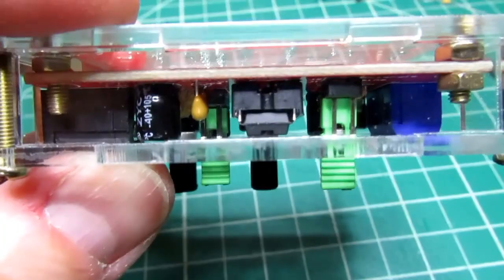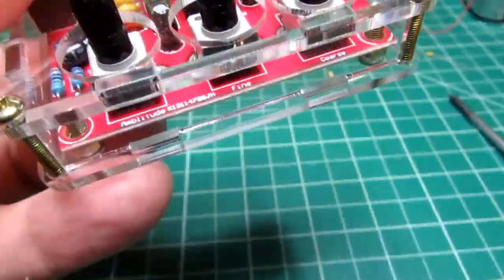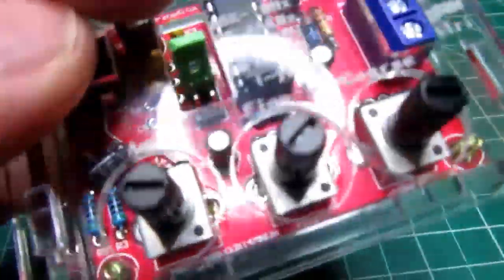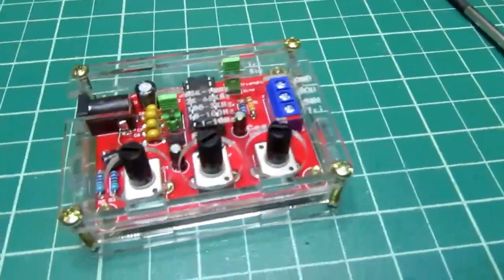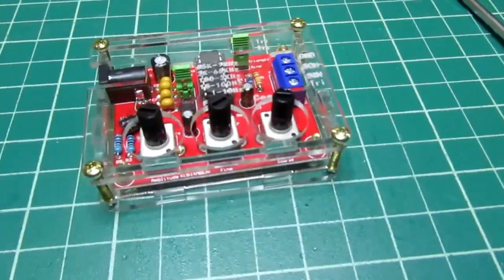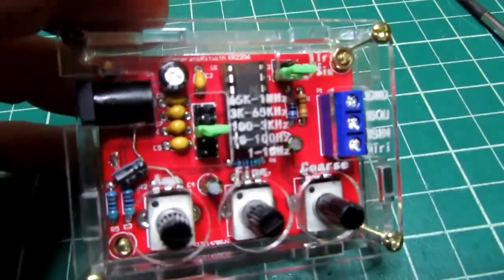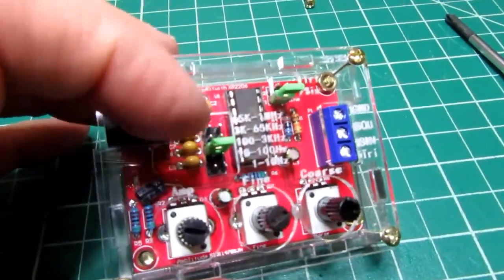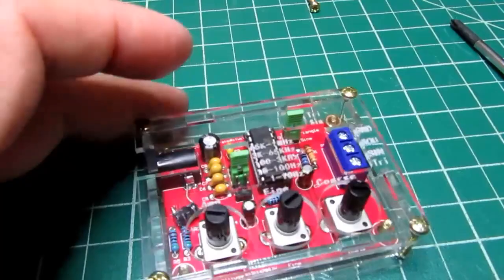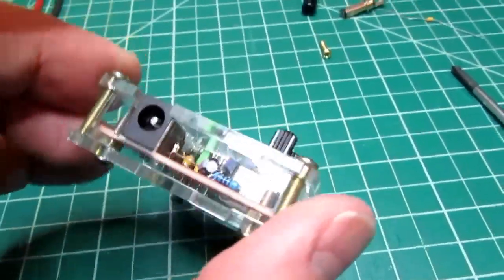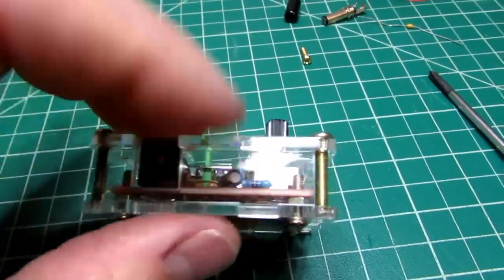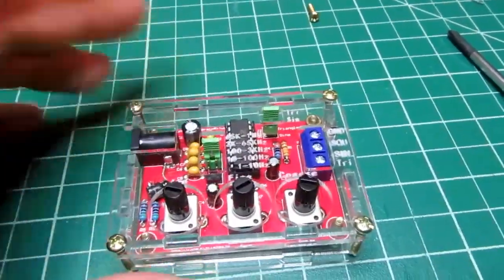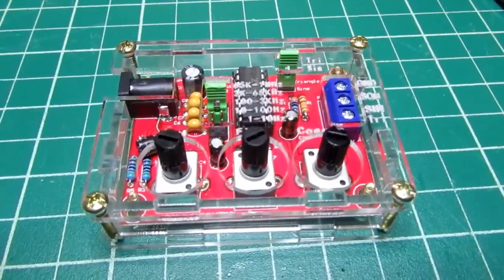The IC almost does. This other small electrolytic here and this one are the same height. They didn't make this any taller than they needed to. That's probably a good cautionary thing. Make sure you push those electrolytics all the way down to the board. Otherwise the case will not come together on these side plates because they're just the same vertical dimension.